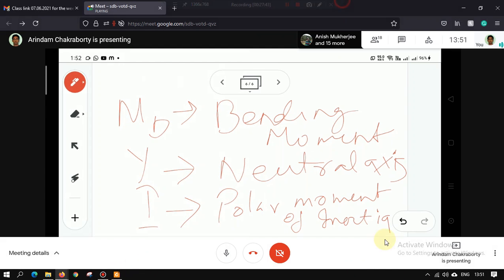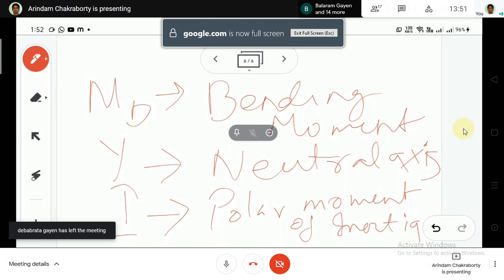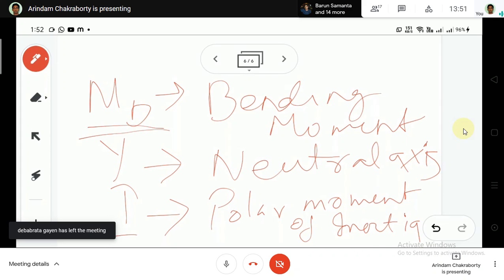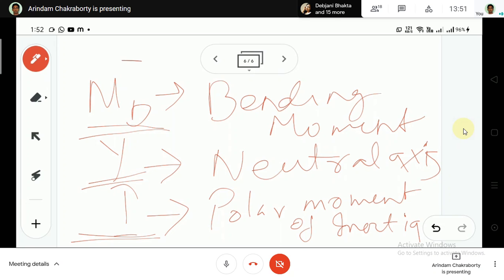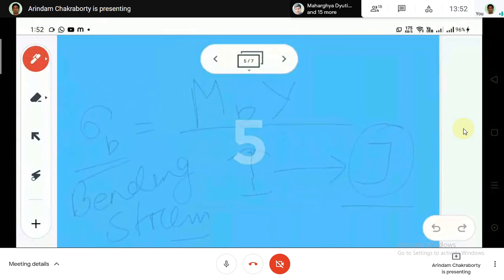But as I have stated earlier, it's a very easy subject, so you don't have to worry about it. At first we have to find out what is M b. Next we have to find out what is y. Next we have to find out what is I. Before getting to all this, we have to see the diagram again. Now what is M b? Bending moment.